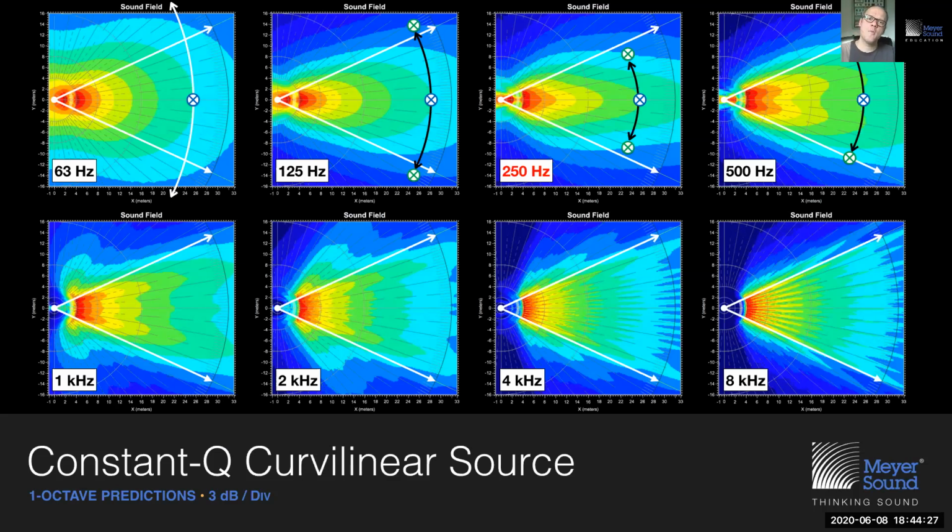But as we go up 1 octave in frequency, then we actually can identify our -6 dB points, and we notice that the beam has become narrower because now line length, the length of the array, starts to do its thing. And then for the same 11-box hang, we actually see that around 250 Hertz, our -6 dB point lives within the slice of pizza.